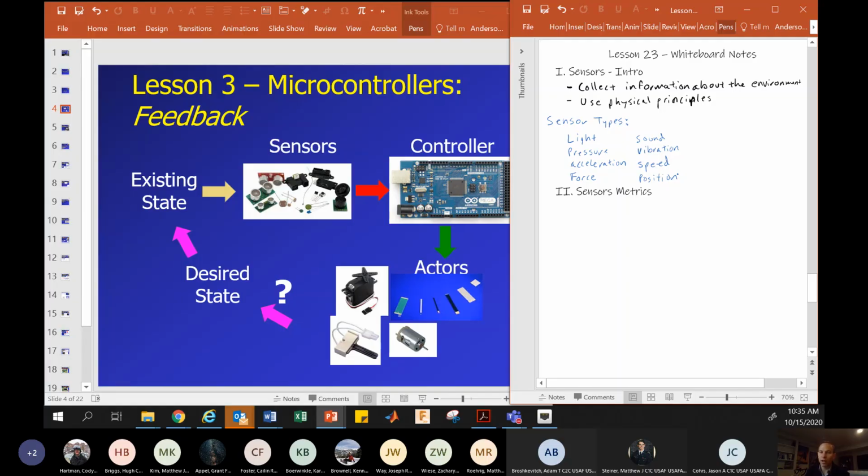You have a wheel that's in contact with the ground, and we keep track of how much it turns, how many times it rotates, and we can extrapolate how far the car has traveled. With a flying vehicle, you don't have anything in contact with the ground, so you can't do a physical odometry in that way. So we use cameras to do visual odometry. Okay, so you said someone else. So Matt said odometer, and that's a position sensor. What else, or a distance? Temperature. Yeah, temperature. Very good.